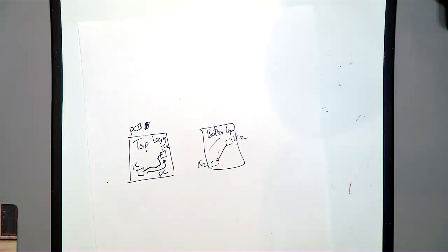Then another concept is the path of least impedance or inductance. At high frequencies, when the frequency increases, current follows the path of least inductance. What will happen is, you have got the ground plane, your signal is going through this copper track, but then the return current will also follow the same, just under it. This is the top layer, so the return current is confined under the track. It is not a straight line. The straight line is the path of least resistance, but when the frequency increases, it will confine under the track.